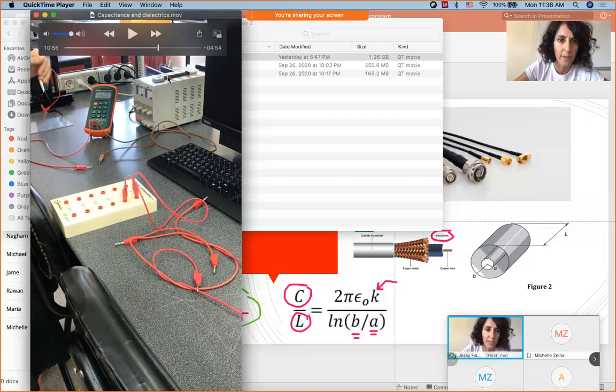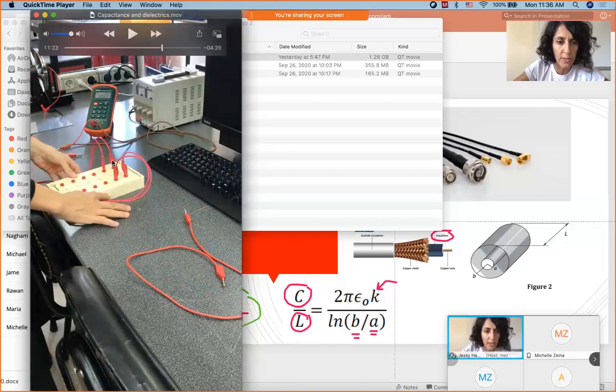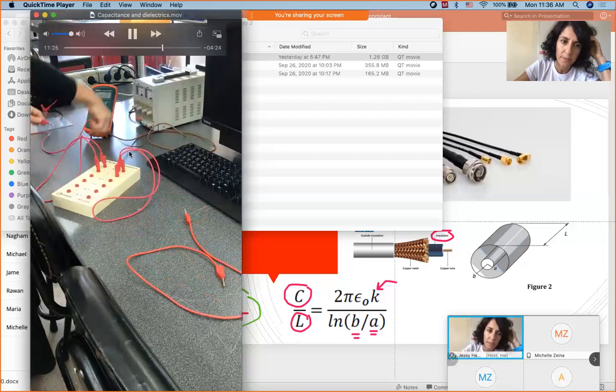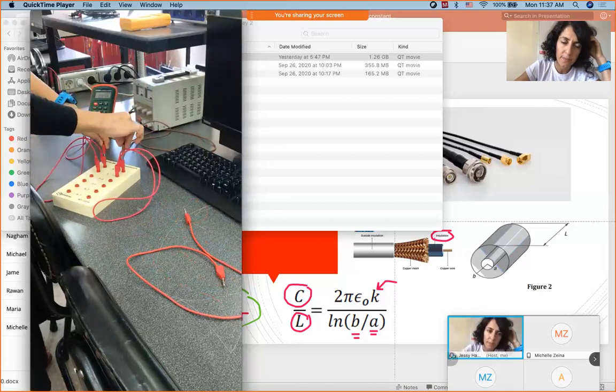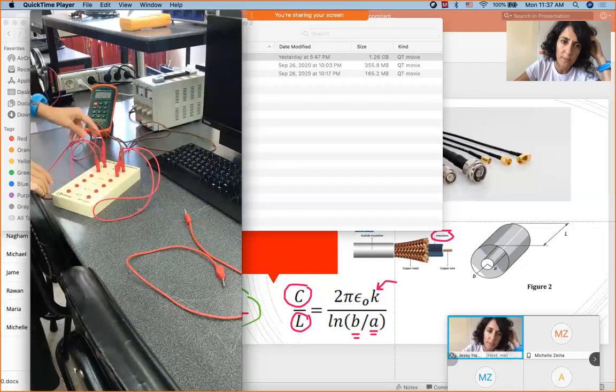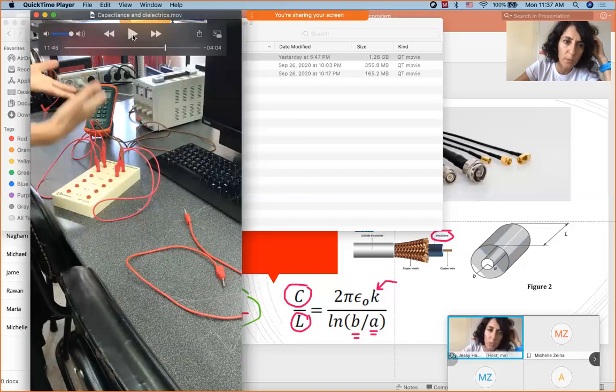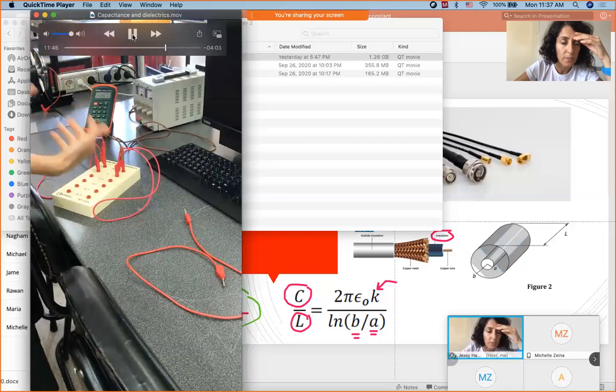Do you understand? And then you will be asked to connect these in parallel. So I already connected them in parallel. Now I can connect the LCR meter to one of them. The LCR meter will be measuring the total, or the equivalent capacitance, of my combination. So what you read here is not C1, nor C2, but C equivalent, which is C1 plus C2 in this case, since you have the parallel connection. You're doing this, and so on and so forth.